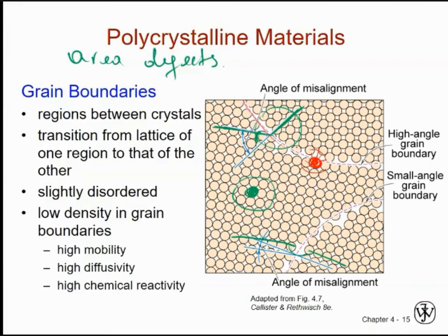So atoms on grain boundaries are chemically active. They have higher energy than atoms inside the grain. That's why grain boundaries have higher energy compared with the grains themselves. That's why if I apply some chemical on it, grain boundaries will dissolve first. With high energy, they go into chemical reaction first. And after that, the grains themselves go into chemical reaction. And we use this kind of phenomenon to analyze phases, grains, and grain boundaries in polycrystalline materials.